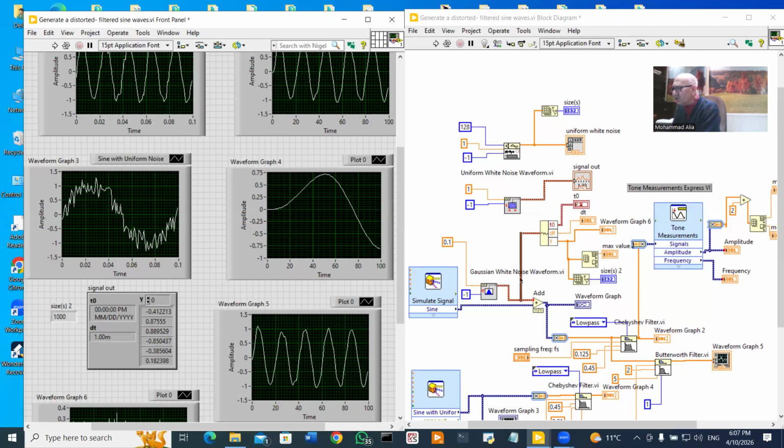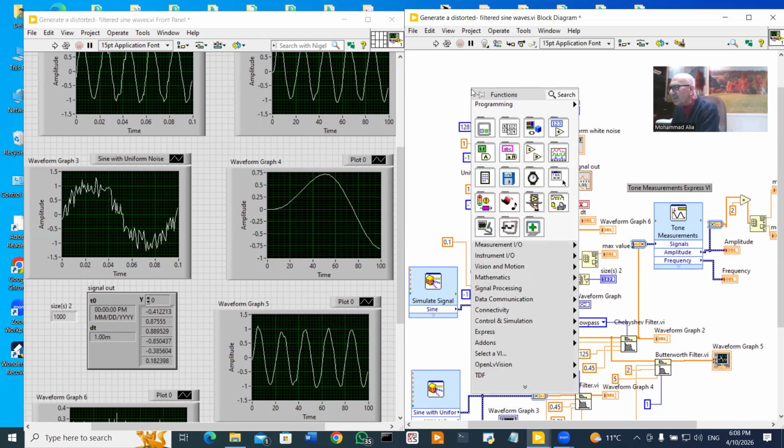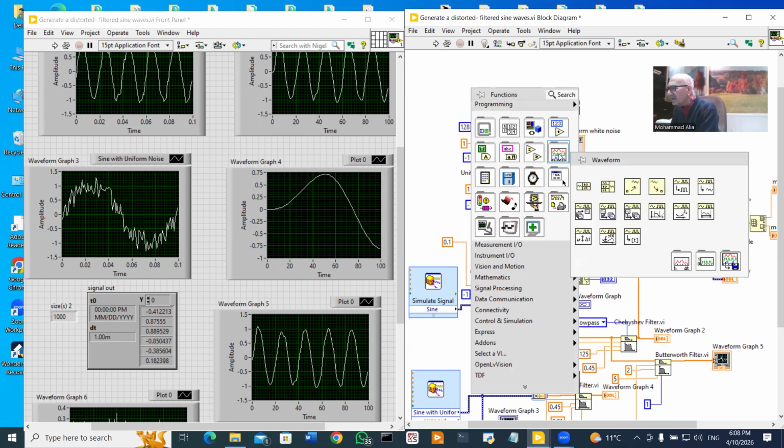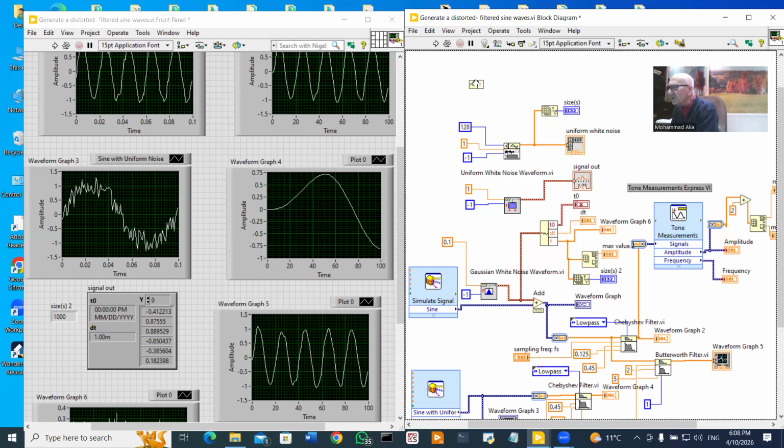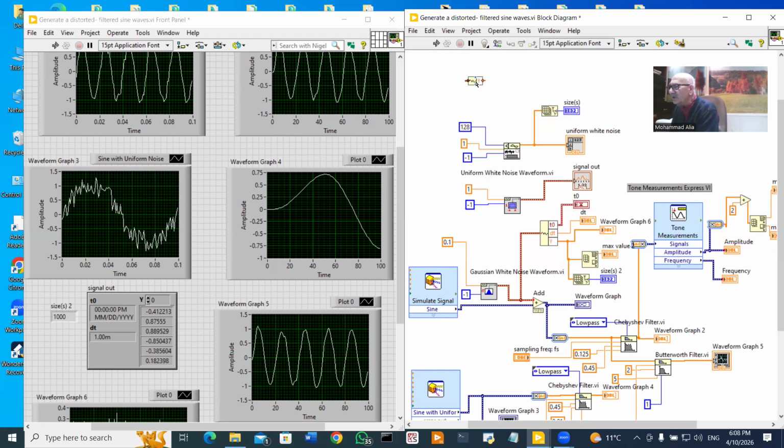It is called a waveform in LabVIEW. You can, of course, open this cluster again by using this piece of code, which is called here, as you see, Get Waveform Components. If you press it and put it on the diagram here, you will have it in this shape. You can expand it. And now you can connect the general signal, which is feeding it, as I did here. And you get at the output the components and have readings of it.